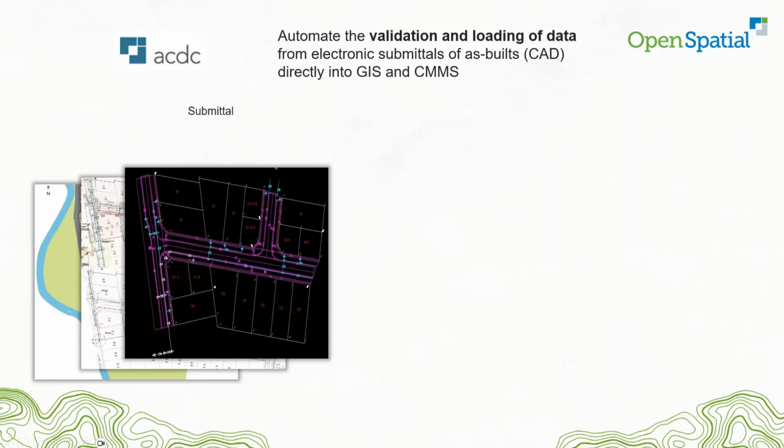And then you can get on utility networks, where we have a strength. You can also do things like check the actual upstream invert elevations coming into a point feature, whatever it happens to be. Are they consistent with the direction of the line, and are the elevations consistent? And you can check the from and tos and build out essentially the core basis for a utility network. You still have to do a little bit of checking and work, but that can be built.